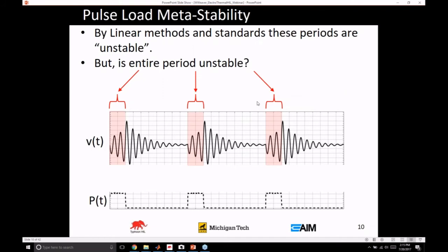The eigenvalues would be in the right half plane, the real parts of them, or any of the other favorite methods to analyze the stability. But that system would say it's unstable, and by many accounts, that would be the end of the story for a lot of previous approaches to the design. So if I had a pulse load that gives a power that shows by linear methods that is unstable, the whole system is just kind of thrown out and not considered.